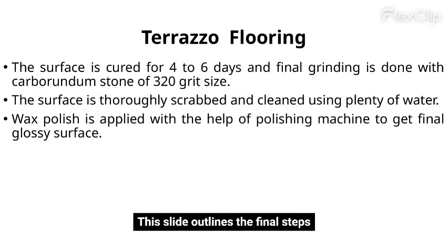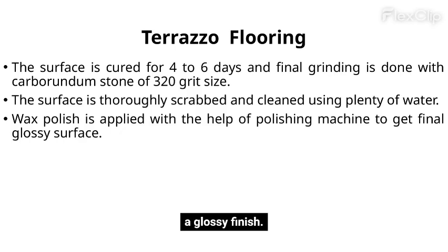This slide outlines the final steps in terrazzo flooring installation. The surface is cured and then ground with fine carborundum stones. After scrubbing and cleaning, wax polish is applied to achieve a glossy finish.